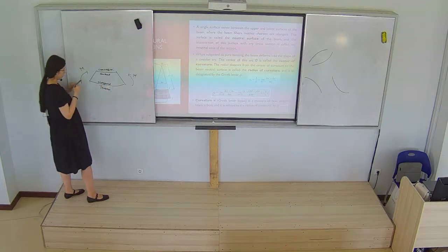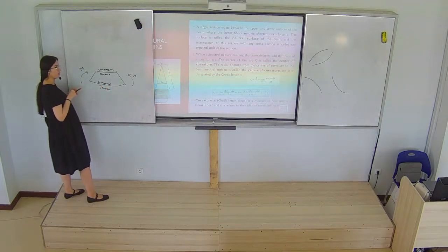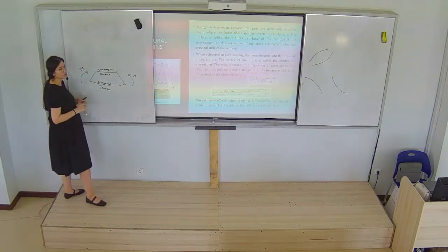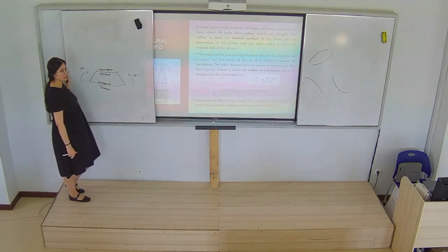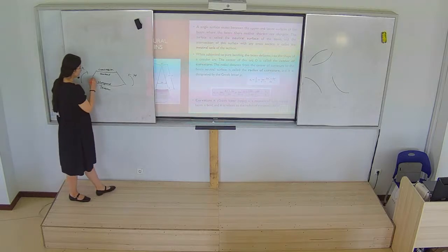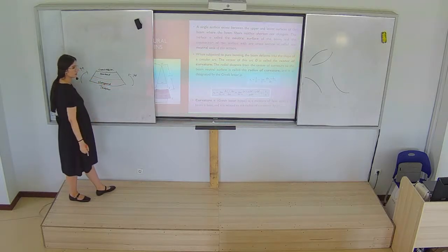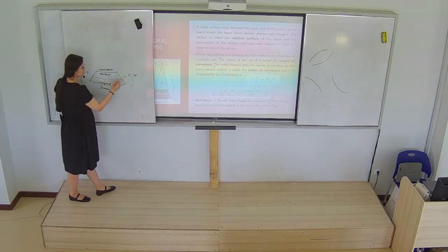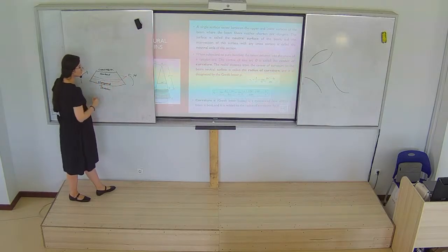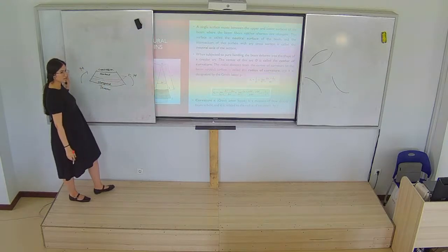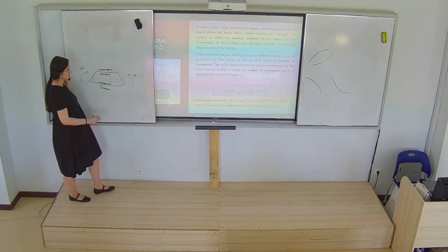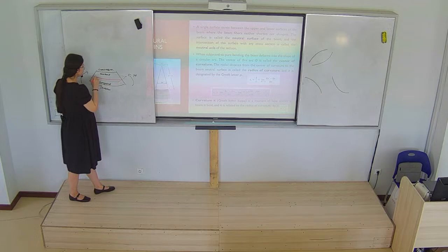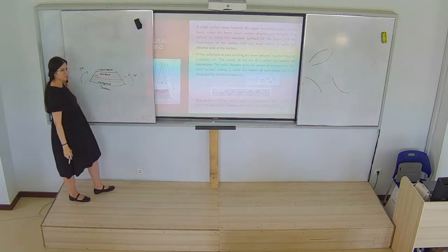But we will have one more fiber which doesn't change its length. It cannot be shortened or elongated. And we will call this one the neutral axis. And the plane which contains the neutral axis, we will call the neutral surface. Compression or tension doesn't happen in this neutral surface. And this one is the neutral axis. Did you understand?